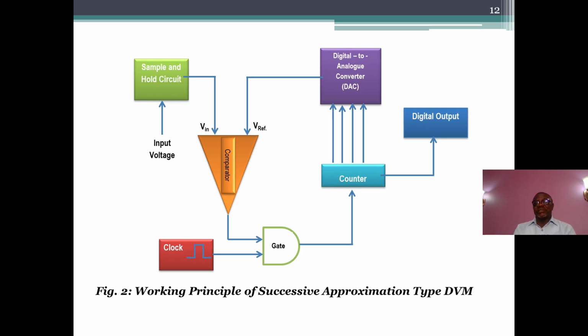So this is sent back to the digital to analog converter. When it is sent, it forms the input to the next level of Vref. What is coming in again from the Vin will be compared with that which is being fed to the Vref. If it is still higher, the same process repeats.